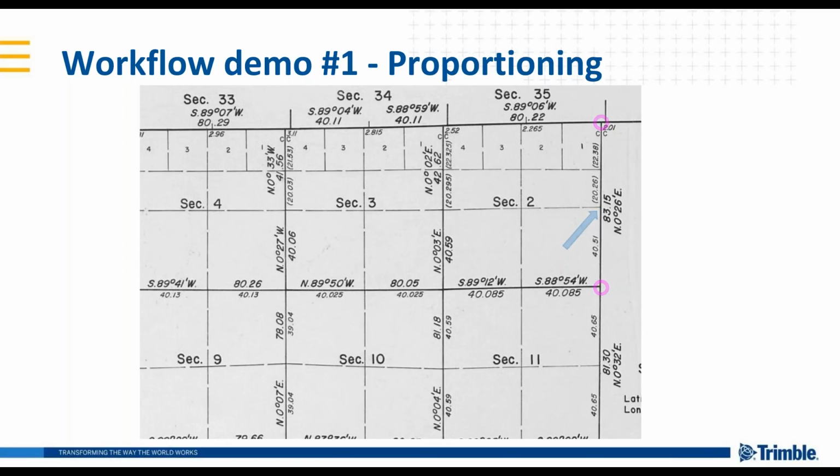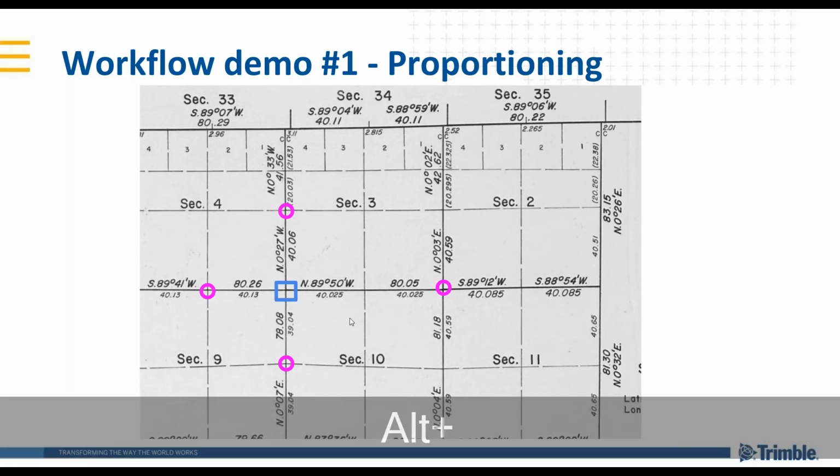That's single proportioning. For double proportioning, it's if we've got a marker to the north, east, south, and west. Double proportioning, in a sense, does single proportioning twice, but there's a little bit more to it. You take your bearings, you convert them to your cardinal equivalents, and then you follow the rhumb line between the two markers in each direction, and that's how you establish the point in double proportioning. All right, and this is the point we're looking for.